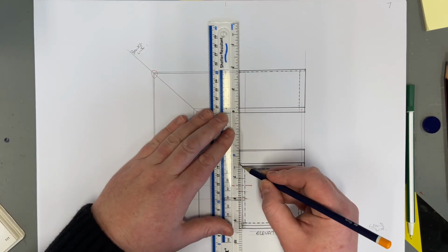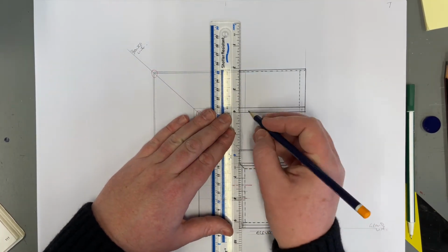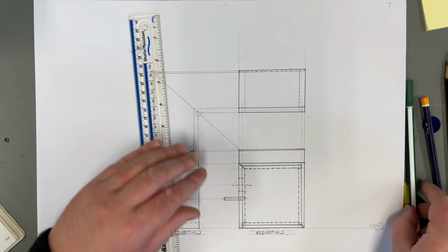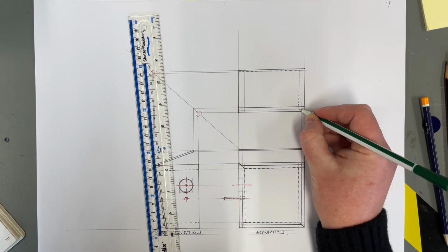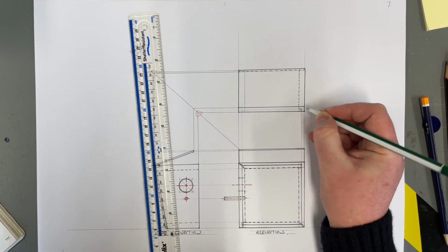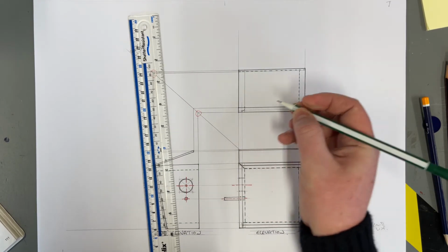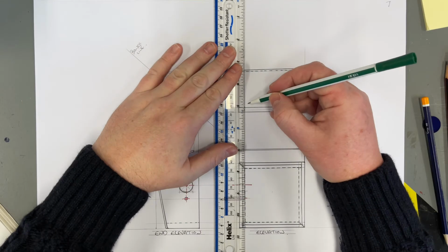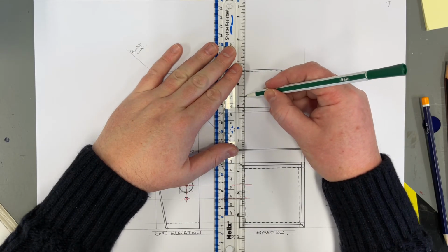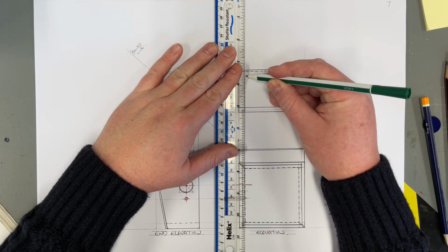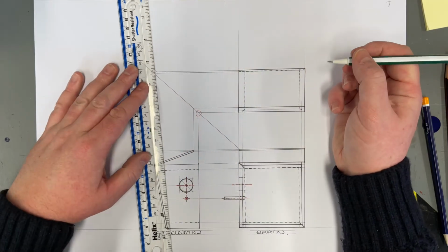And then plastic here, up, projected across. So that would sit just in there like a little L shape. At the opposite side, this would be a mirror reflection of that. Okay. Short dashes. That's hidden detail all the way up.